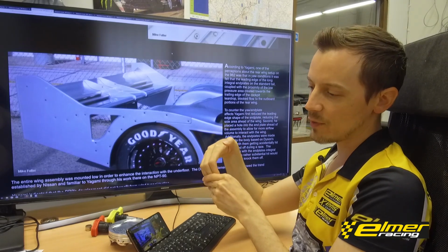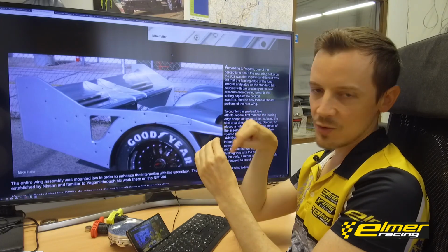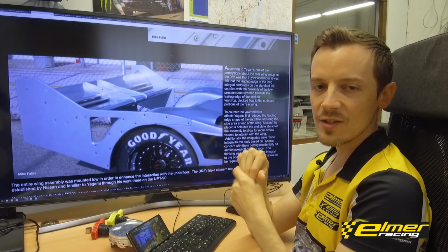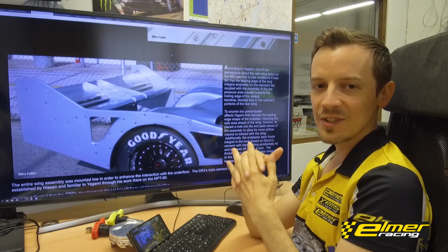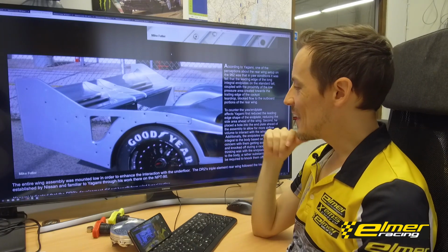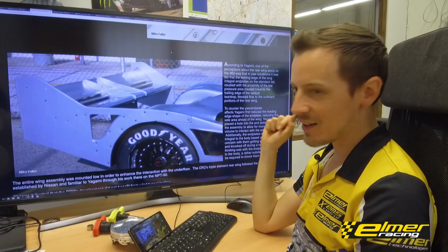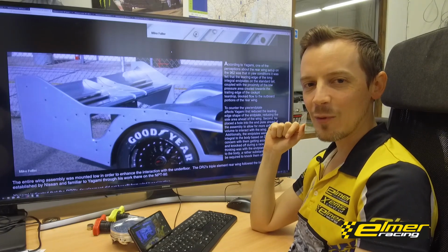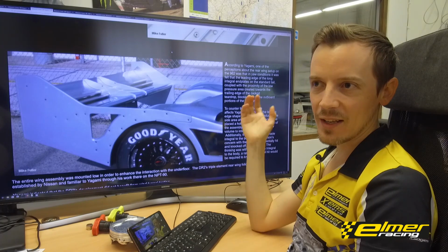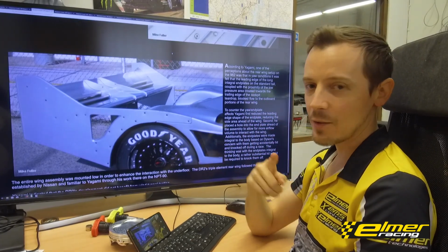And once the tire gets very flat, the sidewalls start getting too high of a sort of fold there, and then you will of course destroy the sidewall of the tires and have an unscheduled tire explosion at high speed. So yeah, if you see cars that have a really low profile tire and are claiming high top speeds and high downforce levels, then they're probably missing something or lying, or you have some artist's impression of the car or something like that. Just another thing to keep in mind.